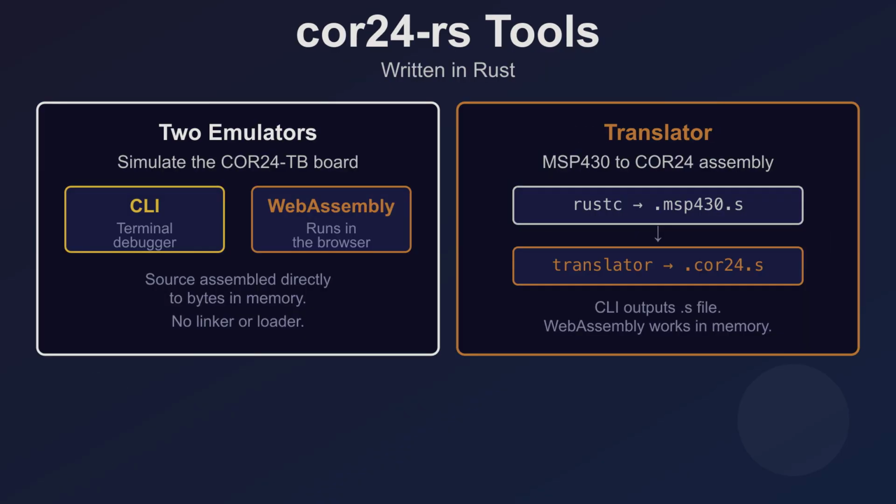My tools are written in Rust. 2 emulators simulate the board, one for the command line and one compiled to WebAssembly for the browser. Both assemble source directly to bytes in memory, no linker or loader. A translator converts MSP430 assembly from the Rust compiler into COR24 assembly.